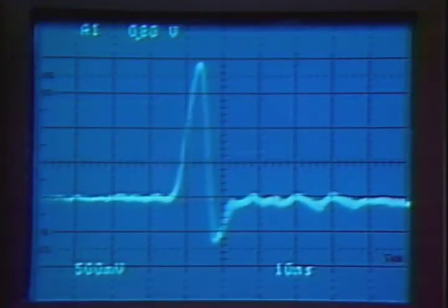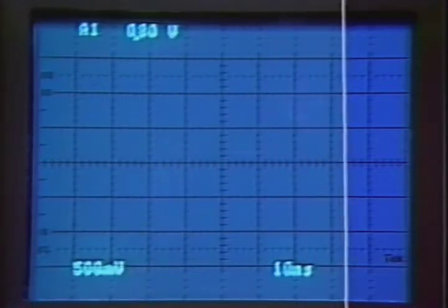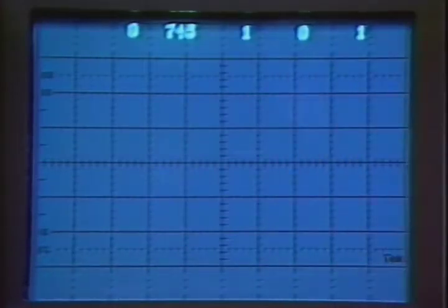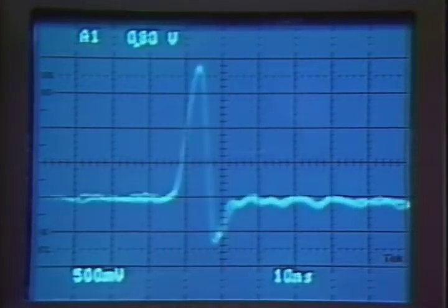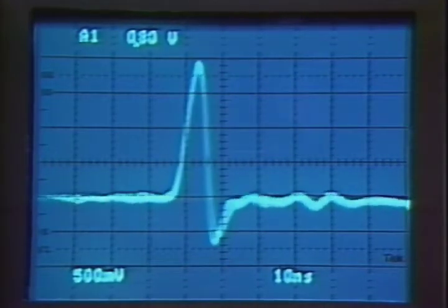The scope monitors itself. Channel plate CRTs can deliver so many electrons to the phosphor that they can shorten their own lives. The 2467 automatically monitors this current and drops the intensity a few tens of seconds after the last front panel control change. A few minutes later, it automatically shuts down the intensity altogether, then flashes a shutdown message periodically to remind you it's still on. To restore the intensity, just move any front panel control. All this conserves CRT life.